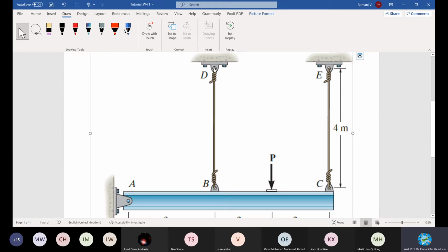And these rods, they call this a cable. Cable 1, cable 2, right? And these two cables are fixed to the support here at this point and this point. Again, it's a kind of pin only. At this point is a pin, and although it is fastened into the wall, the joint is just a pin. These are all the conditions.